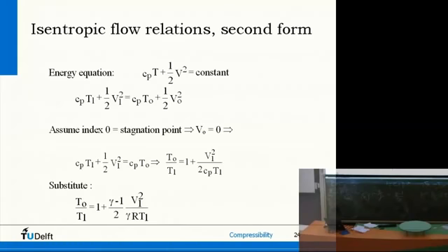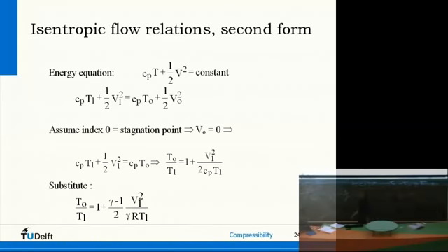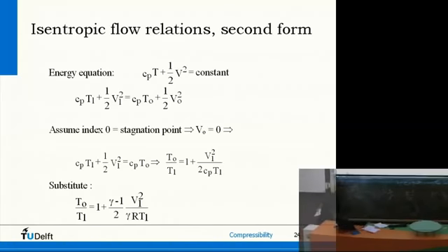So what I did, starting with R is equal to CP minus CV, divide by CP. So R over CP is 1 minus CV over CP. Then I realized this CV over CP is 1 over gamma. 1 minus 1 over gamma. And then I put them all in 1. So I say, okay, this 1 is gamma over gamma. So gamma minus 1 over gamma. So what is CP actually equal to? CP is equal to R divided by that one, divided by gamma minus 1 times gamma.